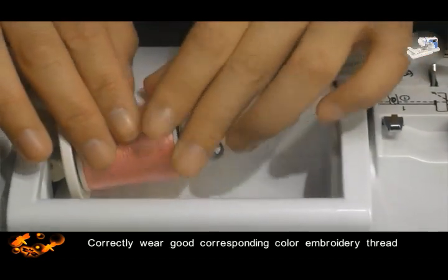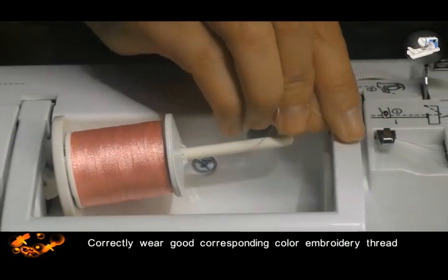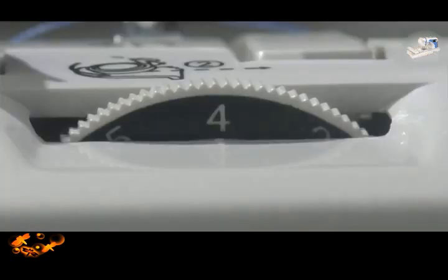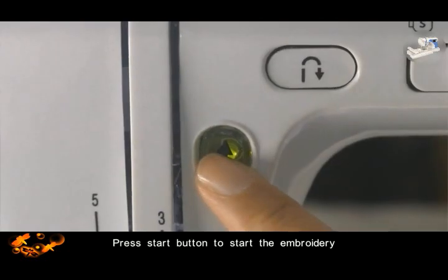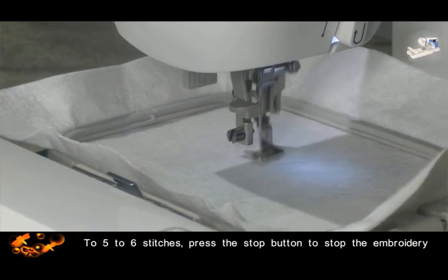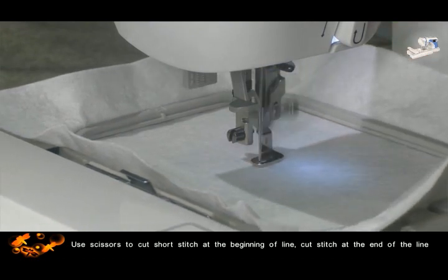Correctly thread the corresponding color of embroidery thread. Adjust the thread tension between 0 and 1. Press the Start button to start the embroidery. After 5 to 6 stitches, press the Stop button to stop the embroidery. Use scissors to cut the short stitches at the beginning of the line, and cut the stitches at the end of the line.